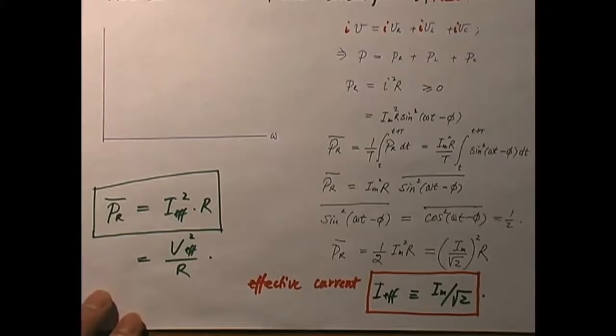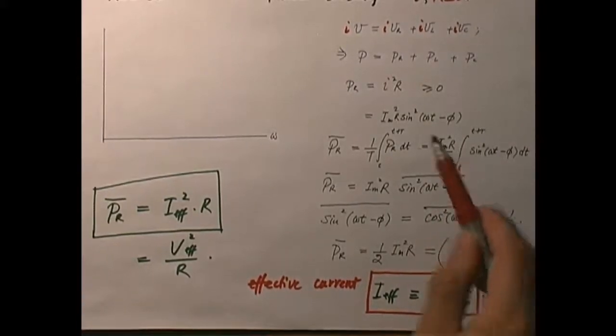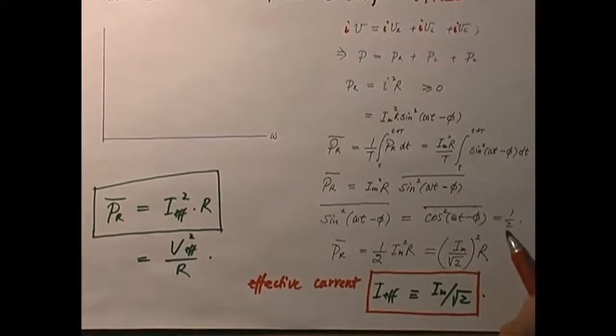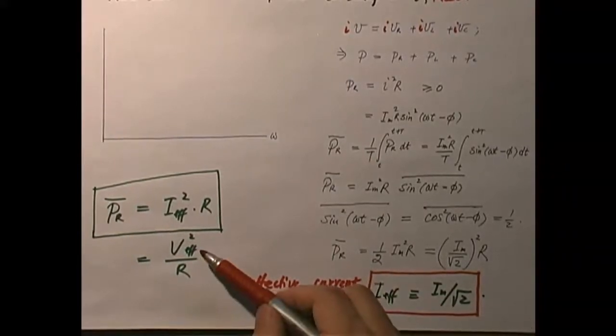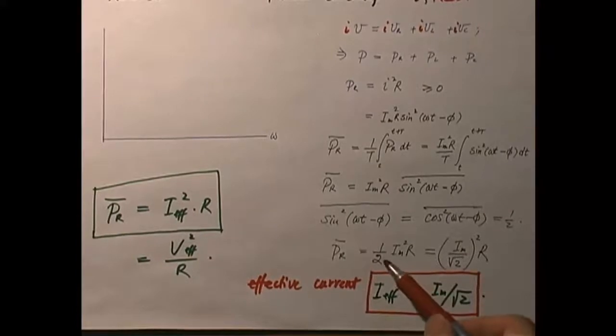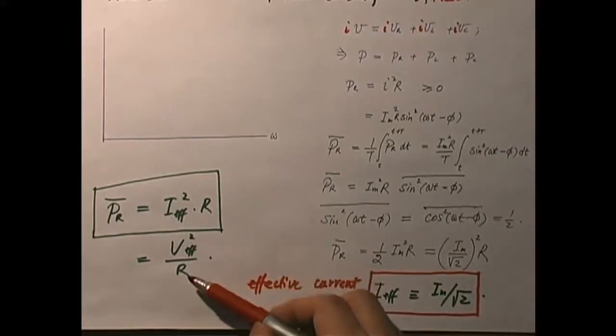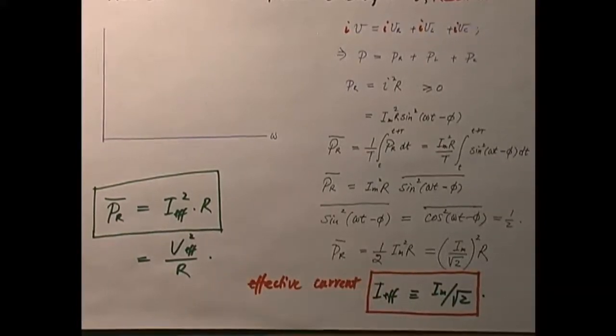But as far as time average value is concerned, you really have to take the peak value and divide it by the square root of 2. You really have to do that, right? But few people would notice that. So it's much easier if they simply told you V effective, because that way you don't have to worry about this 1/2. You simply take that V effective squared and divide it by R. So that 110 volts really is the effective value of the EMF that's delivered through the power grid.